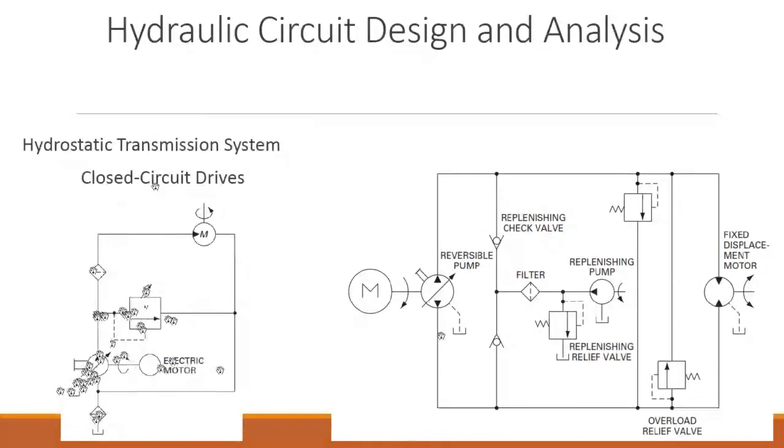Now the oil goes through this strainer or filter to the motor, and then it turns the motor. When it does the work, the oil goes back into the line after the hydraulic motor, of course at low pressure. There is no way elsewhere because it's closed already. It comes here, and the pump is continuously working, so as soon as the oil comes here, the pump pulls the oil back into the circuit, and this oil keeps on circulating like this.